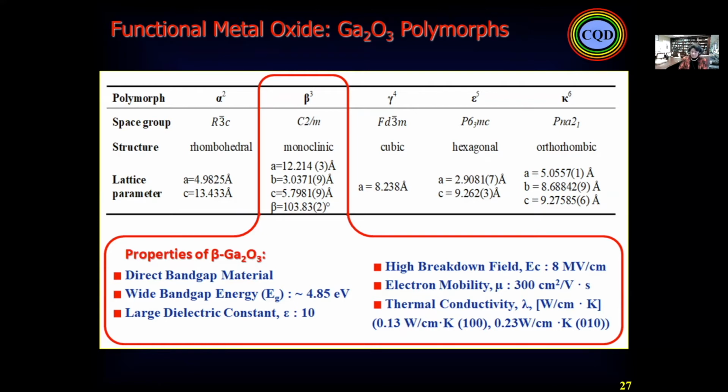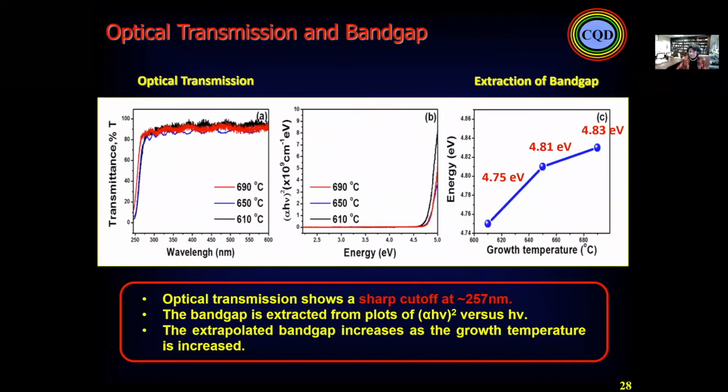One of the problems of this material, similar to gallium nitride at the beginning, is that nobody can make p-type in this material. So just 2 years ago, they came and asked me to be involved. By intuition, I tried immediately to put the silicon with the gallium, and we tried to demonstrate excellent performance, the p-type transistor. But I found that the silicon can play an amphoteric behavior to give the p-type.